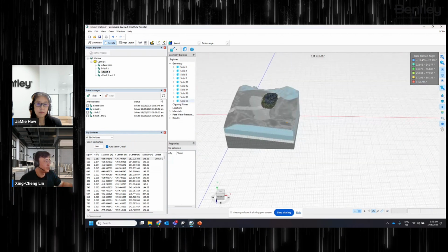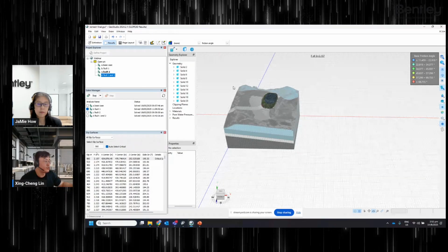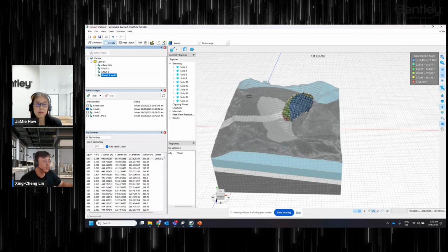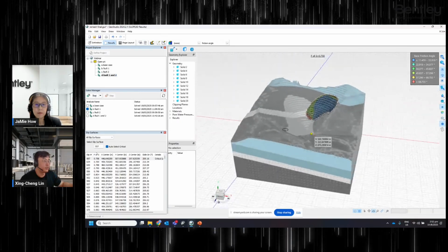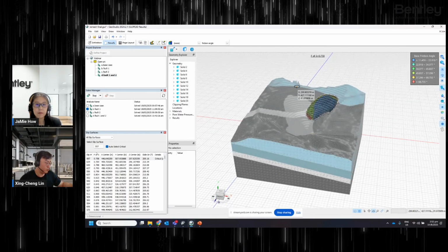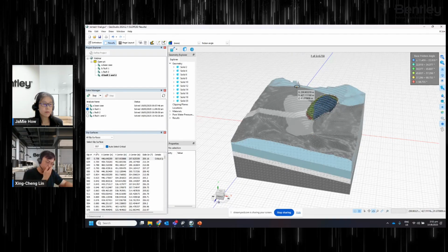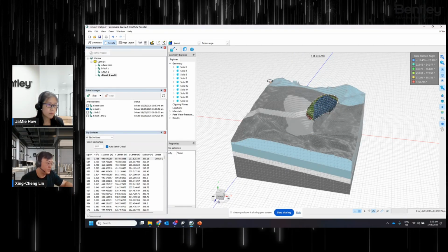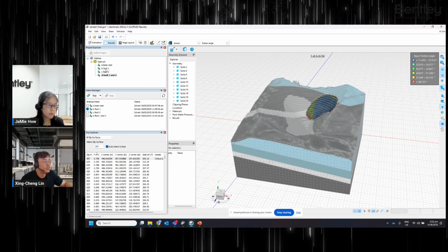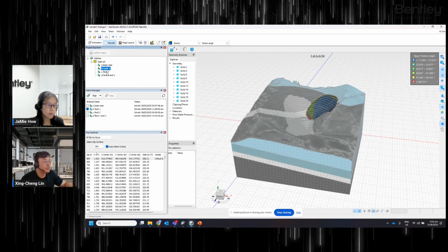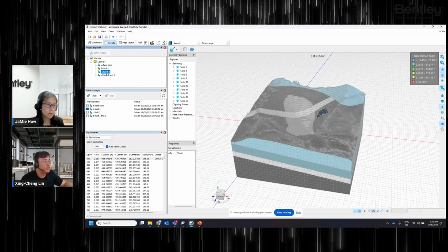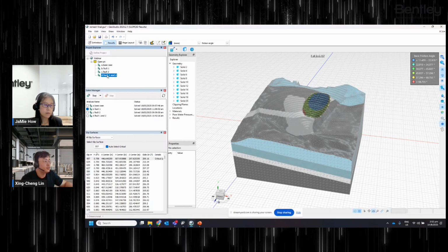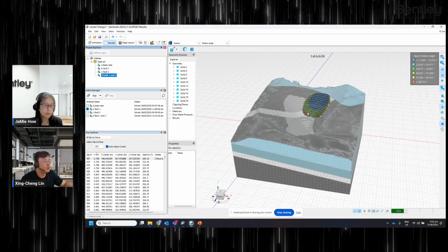Switch it back. So case number D, we have introduced both fault 1 and fault 2 acting together. And this gives us a factor of safety below 1. The critical sliding mass is now sitting somewhere in between the position of B and C. So this is B, okay, C, and now D, so it's somewhere in between.